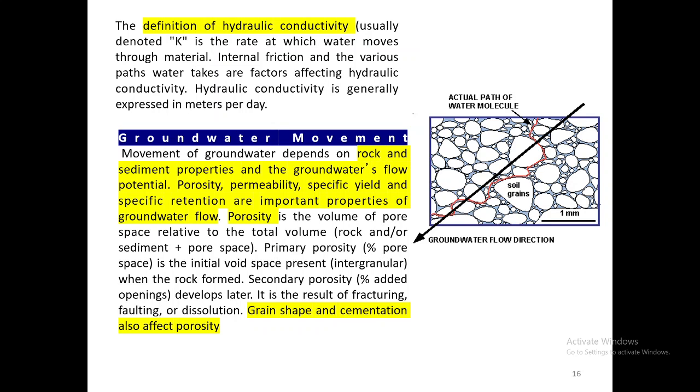So in case that the soil particles are interlocked, then it also can have effect on the movement of groundwater. Thus, porosity will be different. We normally declare that porosity as effective porosity, because that effective porosity is what actually providing us the specific yield. We will talk about it in the next lectures, next slides.